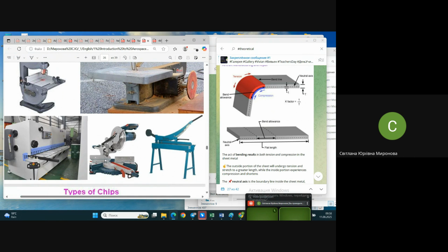But do imagine that you insert it into this right one. It's easy to imagine, I hope. On the left you see the same machine, but the plates are more massive inside. Of course, it's working. Maybe that one is under numerical control, depending. Yes, it seems like it's CNC controlled. It means that the back stopper, this back gauge that we have seen in the V-bending machine yesterday, may move automatically according to the program.